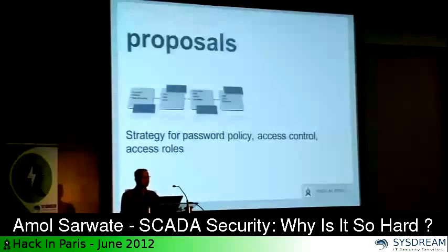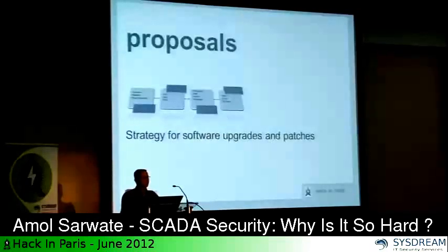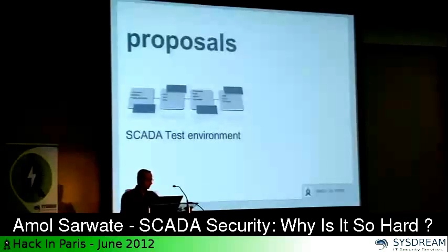Some of the proposals: since a lot of these SCADA systems look more and more like normal IT systems, you should have all the best practices that apply to IT systems, such as a strategy for password policy, access control, access roles, and a strategy for software upgrades and patching. Try to have a SCADA test environment. This is easy to say, but difficult to do, because it's very expensive to have even a small part of your system as a test system.